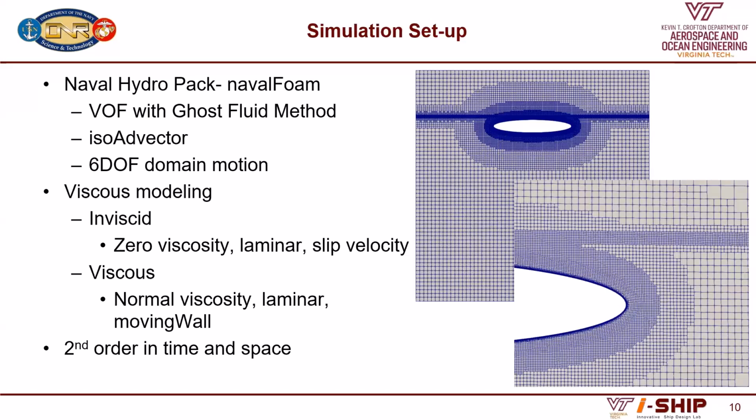These are an example of the near surface body where we refine the free surface to capture those small perturbations on the free surface. We also have a boundary layer around the body for y plus less than 1.